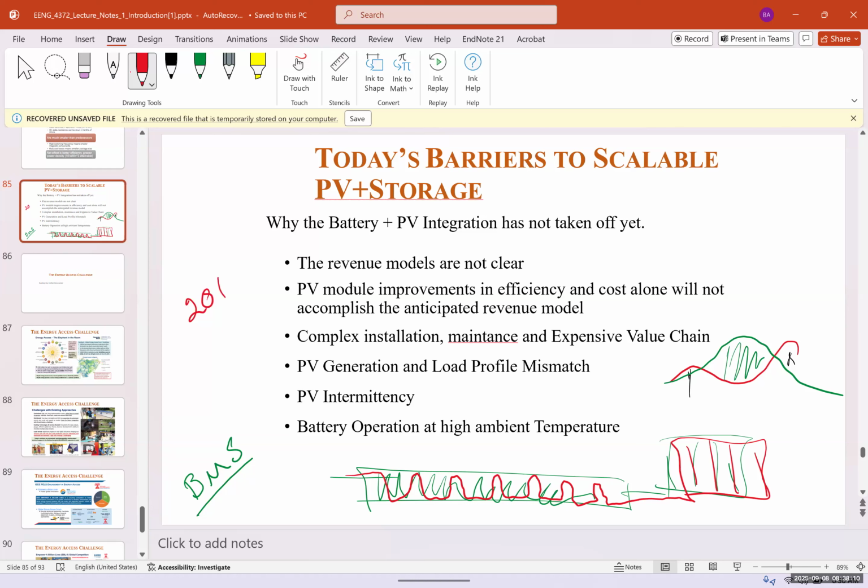The ideal situation for a battery is always to charge it between 20 and 80%. If you want the battery to last longer, never let it go below 20 or above 80%. And the charging cycle is usually 500. Newer generation is 1,000 charge cycles. So from 0 to 100, if it's 1,000 times, it's going to degrade the battery to less than 80%, or sometimes the threshold is 70%, and then it's time to change the battery, and that's the expensive part.